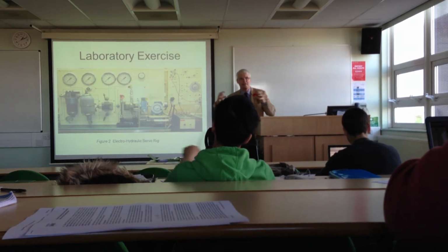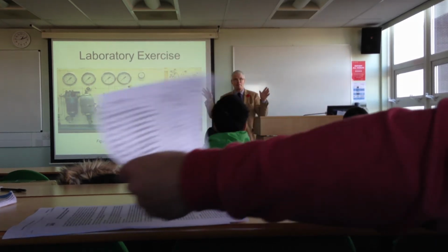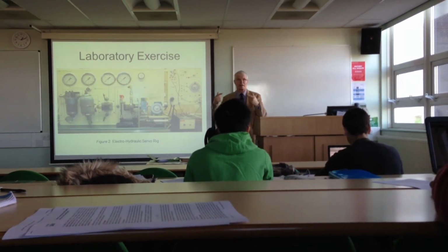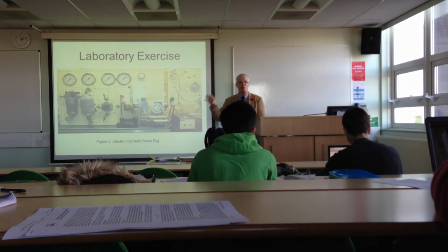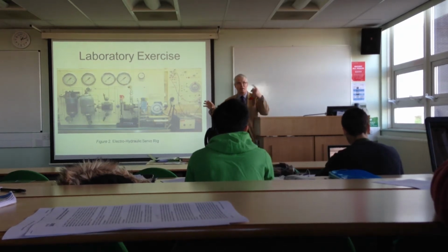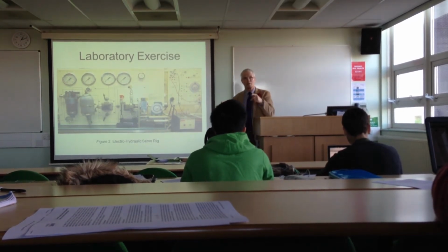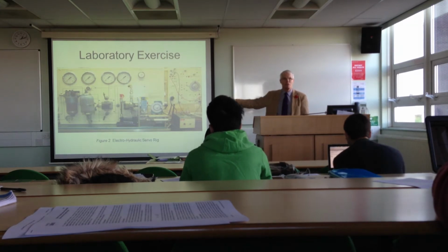So there are two completely separate hydraulic motors. When both hydraulic circuits are fine, they both drive. So the output goes to both wings at the same speed. If for any reason you had to shut one of those circuits down, the hydraulic circuits, they put a brake on that shaft. The other one can carry on turning, and it will still drive the flaps or the slats out, but because we've now only got one motor, it goes at half the speed. They'll still go out. So that's typical, if you like, of the drive.